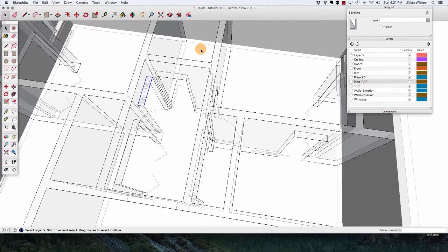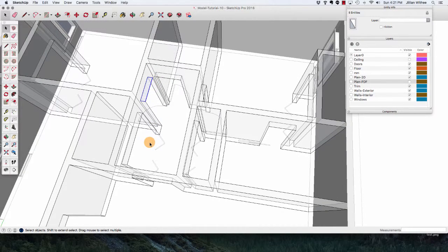And since we're going to be doing the bifold doors as well, let's take a minute right now and go ahead and increase the openings of all the other doors that get bifold doors. And you might as well do this pocket door too. Do that now and then we'll reconvene in a minute.